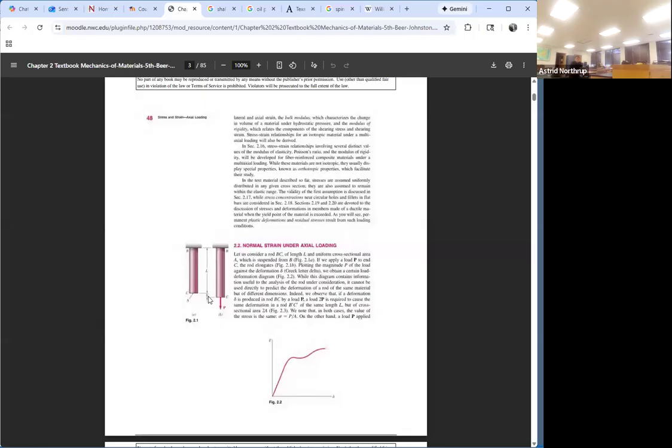The symbol for, okay, so there's 2 symbols. If you look at this one, this is a small delta, which is like this. Delta is not the strain, but delta is the inches or feet, the amount of deformation. If you take delta and divide it by the original length, that is called epsilon, and epsilon is the strain. So you can see that the dimensions of this are going to be length, and the dimensions of this are length. So epsilon or strain is dimensionless.